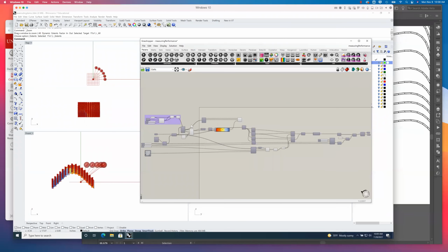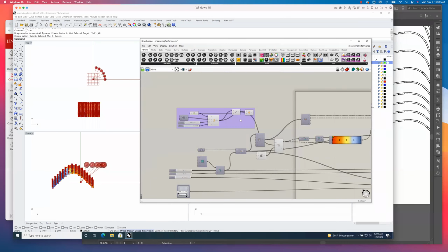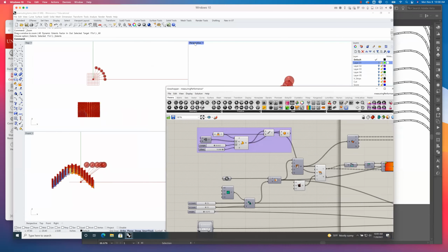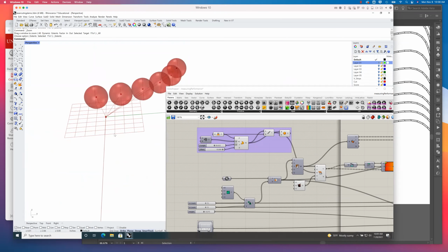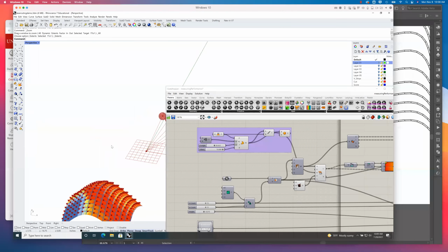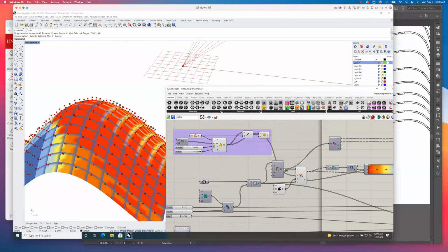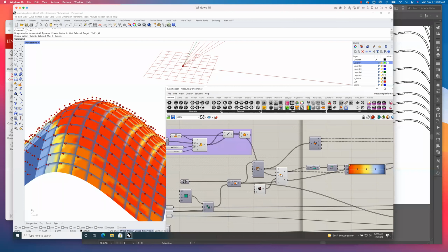All right. So what I've done is I provided rays, and then what this simulation does, this graph, is it takes my surface and it takes each of these rays. It divides this surface up into a set of points, right? Converts it into a mesh, and each of those mesh triangles has a bunch of vertices. And then it populates each of these vertices with these rays, right? And then it measures which of these rays actually hit directly, the angle of their direction. So if they're perpendicular to it, that's going to hurt more than if they're at a more oblique angle.